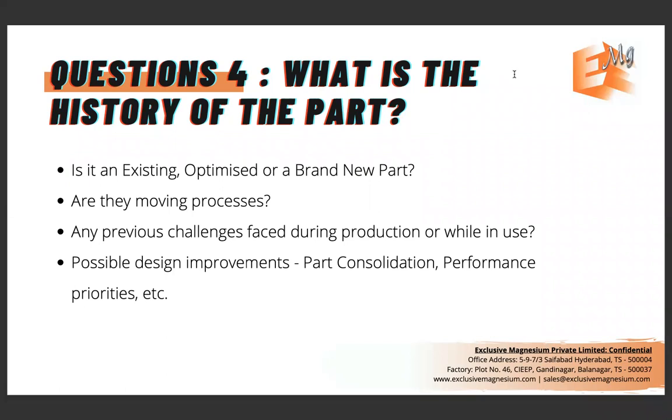But when we asked the same question to them, we understood that all these extrusion products will then be bolted together to make a single large component. And we were able to guide them that instead of doing 7 different or 5 different molds for extrusion, you could do just one die for permanent mold and consolidate all those parts into a single part. So part consolidation is one major element that usually happens when you have these conversations with customers.